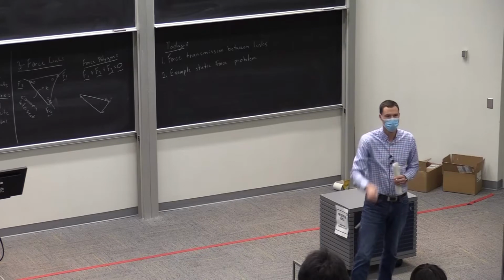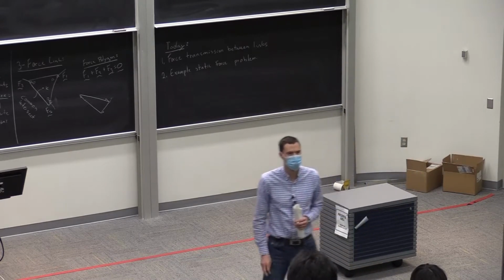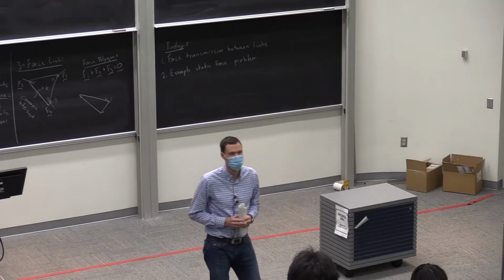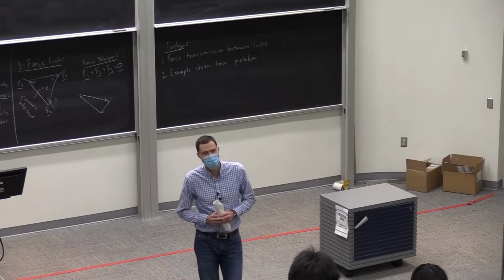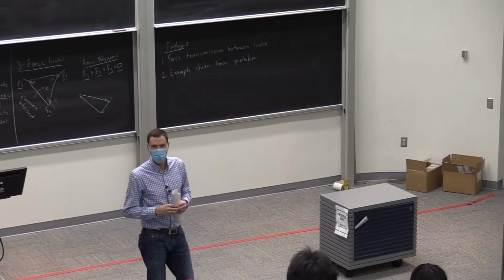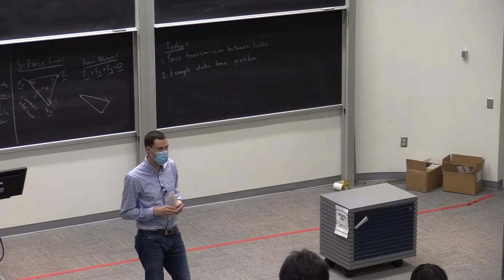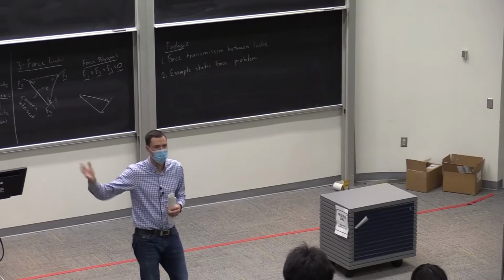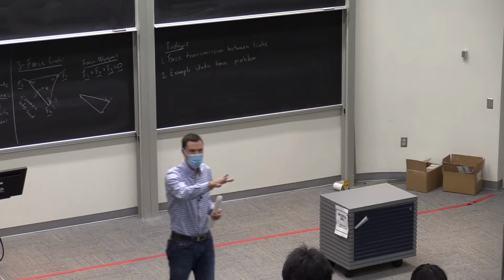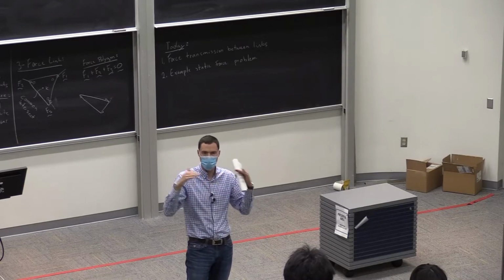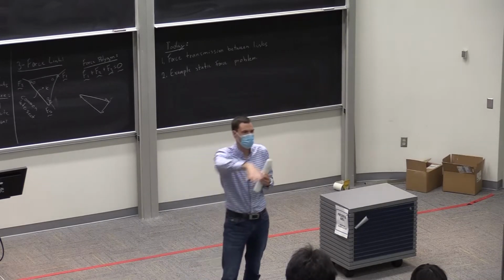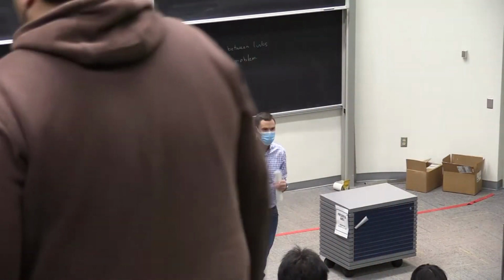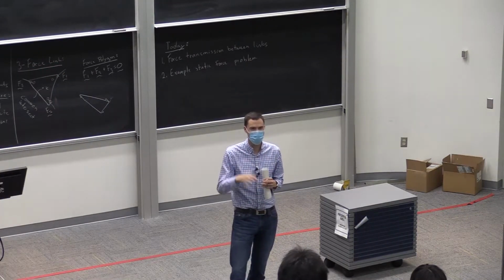Okay, for limit positions, is it always just when it's parallel and perpendicular? Is that what we're always looking for? Because sometimes I don't know what's going on in the mechanism. Yeah, this has been a common question, so I'll give a little general advice for finding limit positions. It's one of the trickier things in the course because there's not a formula you follow and just learn and do. But you're right that I told you they appear when something is perpendicular or parallel. And the thing to look at is the input link. So wherever the input's coming, that's going to be perpendicular or parallel to the next link at some configurations. Those are good ones to check.